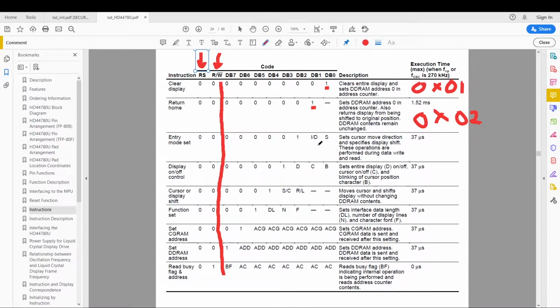of the cursor if we're incrementing or decrementing the cursor. So basically if we are moving from the back of the RAM to the forward side, or if we're moving from the front 00 to the back of the RAM, which I can't remember the ending address, and if we're display shifting. The last bit sets display shifting, which determines how your text will come out on the LCD.